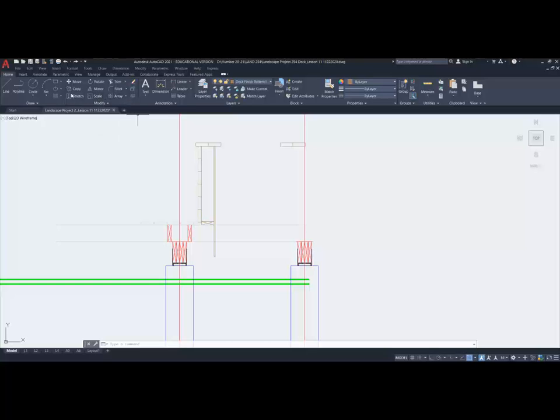And I'm going to draw this here, but then I'm going to change its color. I'm using polyline, and the polyline will go here, and I will bring this straight down, and then I'm going to extend that just below soil level, about 6 inches, and you'll see why in a second. And this I'm going to make thicker. So I created a polyline, so I'll type in P-edit, and I'll select the rubber membrane and give it a width of 1/8 of an inch, 0.125, just so it's thicker.